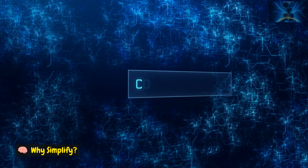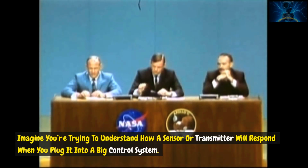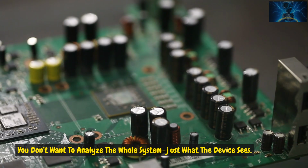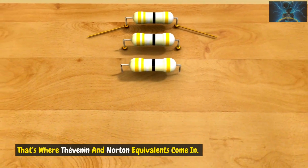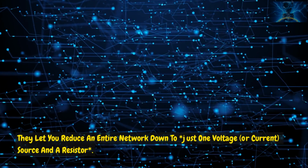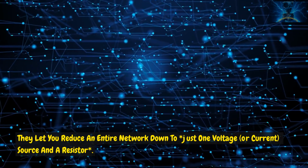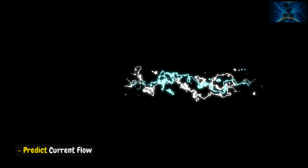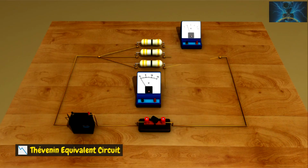Why simplify? Imagine you're trying to understand how a sensor or transmitter will respond when you plug it into a big control system. You don't want to analyze the whole system, just what the device sees. That's where Thévenin and Norton equivalents come in. They let you reduce an entire network down to just one voltage or current source and a resistor. This makes it way easier to calculate voltage drops, predict current flow, optimize load matching, and analyze worst-case scenarios.